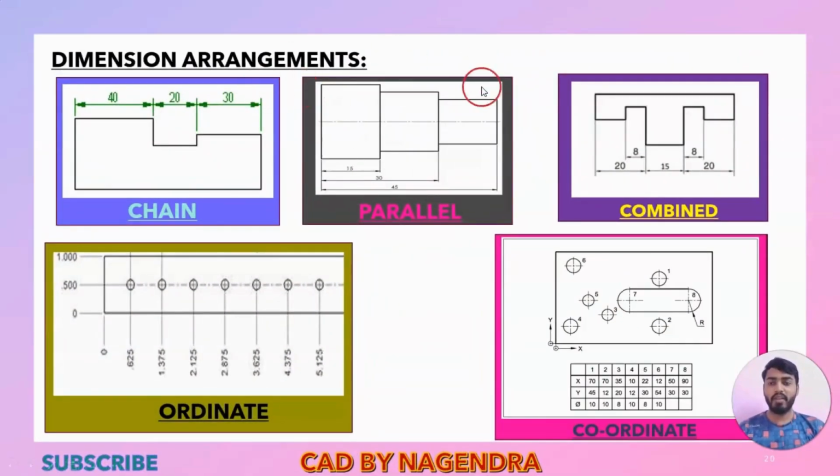Then next we are having different types of dimension arrangements. We are having chain dimension. Chain dimension is nothing but one dimension to one more dimension. Here a chain link will be there, like a continuous link like this. Then parallel dimension is nothing but one dimension parallel to one more like this. See, this is parallel to this, and this is parallel to this, like that. Then combined dimension is nothing but a combination of chain plus parallel. Here you are able to see chain dimension and also parallel dimension in combined dimension.